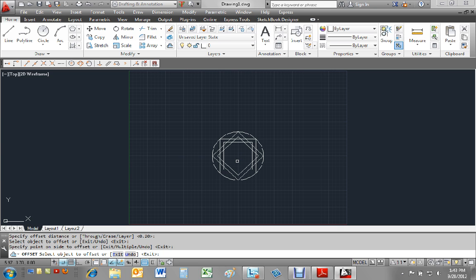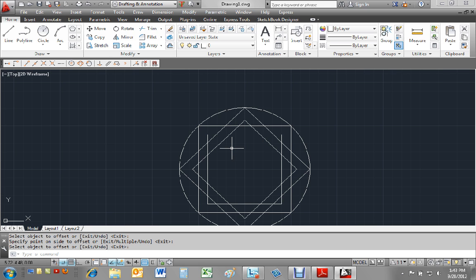It needs to be a 2-inch square in there, and I don't think we've achieved that. Let's see. I think we have. We'll measure. Let's go to measure, and let's measure from corner to corner. I'll turn my snap off. And we'll pick the end point. And let's see. End point. And yes, we have a 2-inch square.